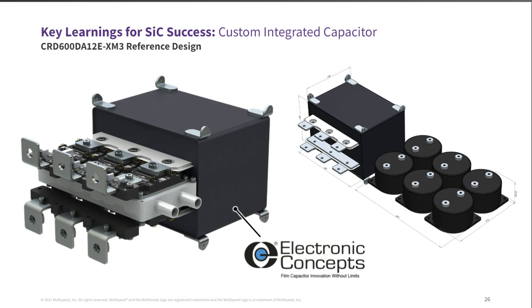So we do take a slight hit in the inductance of this capacitor and DC link busing, but that's a trade-off that is easy to make, in that it doesn't really affect the overall performance of the stack up, but it allows us to achieve a really high power dense design, as you see.